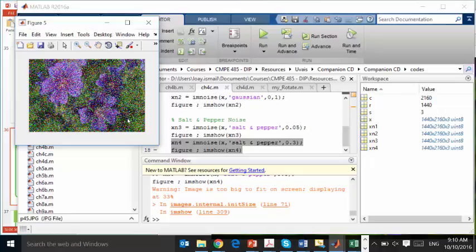In most of the cases, as we'll see later when we talk about these images in the frequency domain, this noise corresponds to high frequency components. So we'll find later that most of the filters used to remove noise are low pass filters. This means that they allow the low frequencies to pass and suppress the high frequencies, which include the noise. But they can include part of the image as well. You see what I mean? The noise has some low frequency components, but those will remain with the original image.